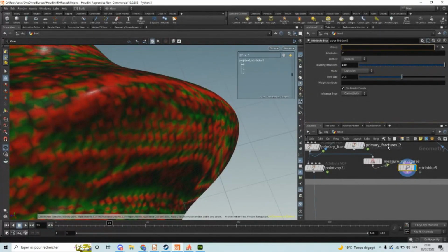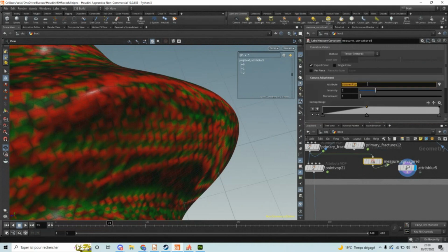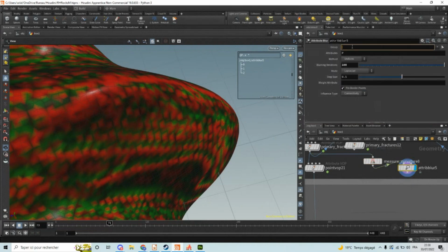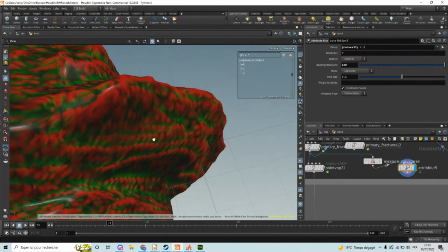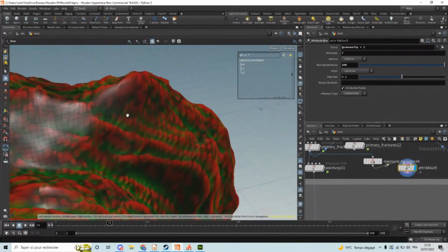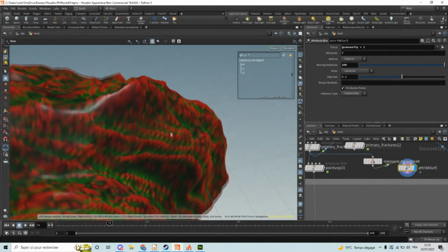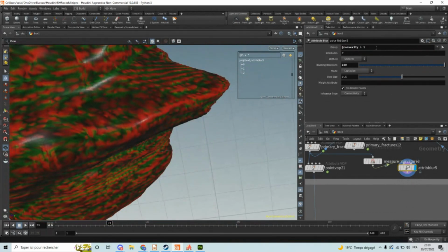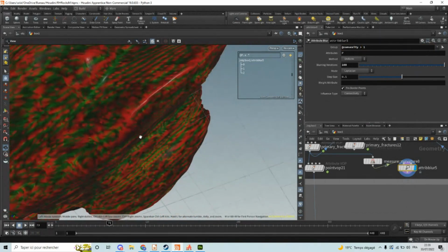But here what I can do is I generated a parameter here called convexity, okay? And I want to make a group which looks at convexity. So @convexity calls the attribute named convexity, and I want that group to be characterized by having a convexity greater than 1. Oh, look at that. Worked. I don't think it actually worked, but well. Now I'm only applying this blur on objects that have a convexity that's greater than 1. So immediately you have a lot more flexibility, right?